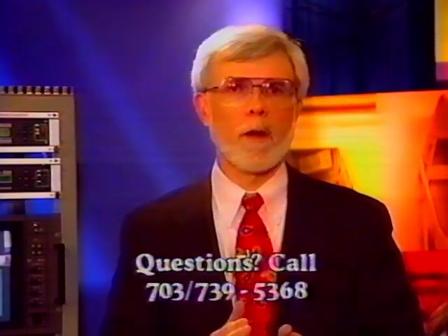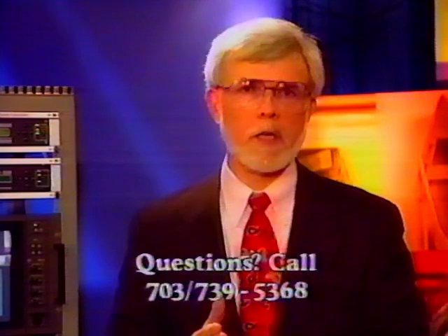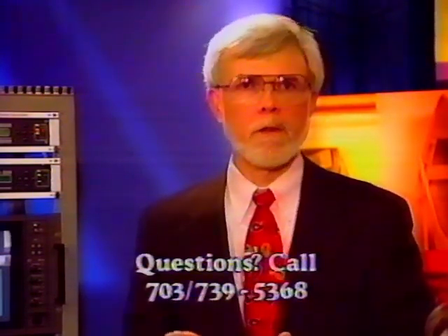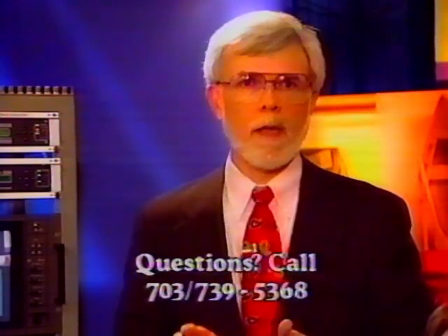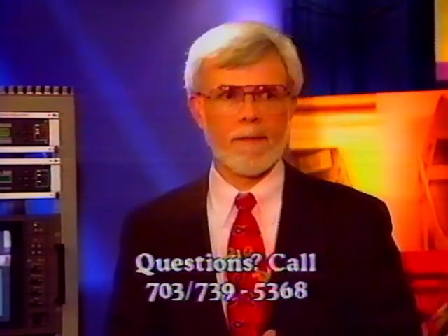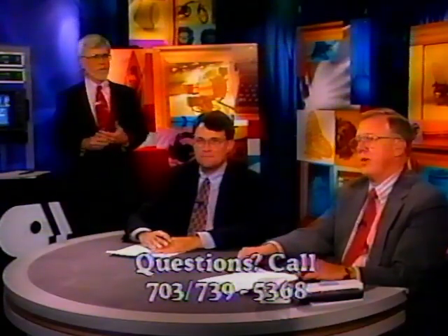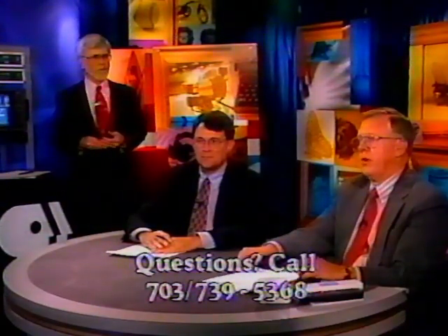So the forward error correction rate is a reflection of the percentage of the raw bits that is applied to correcting errors in the transmitted signal. And just so you understand, the 3/4 means 3/4 of the bits are going into video and 1/4 is going into forward error correction, not the other way around. That's correct.